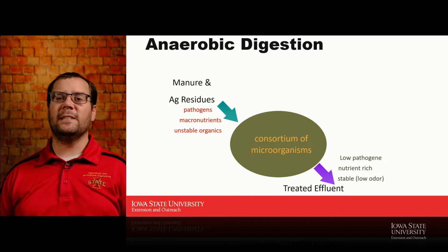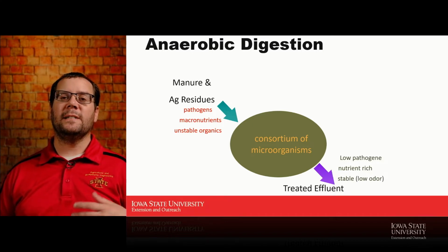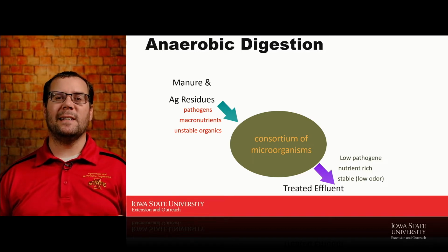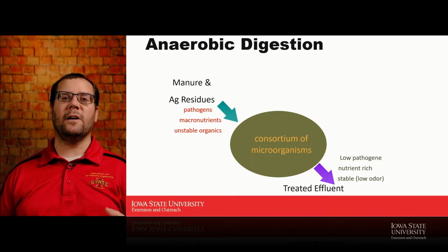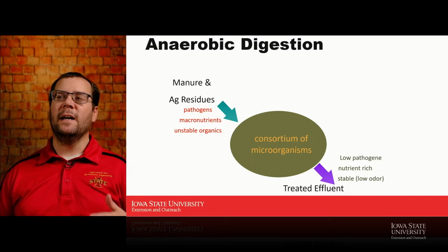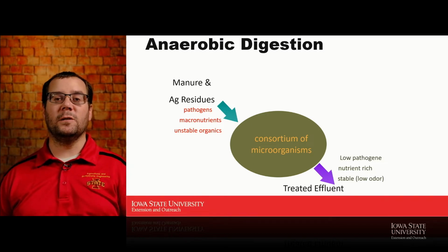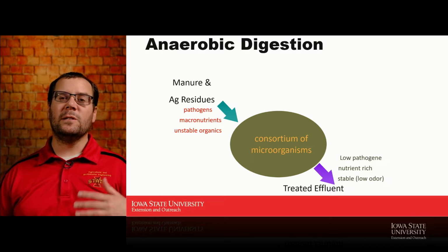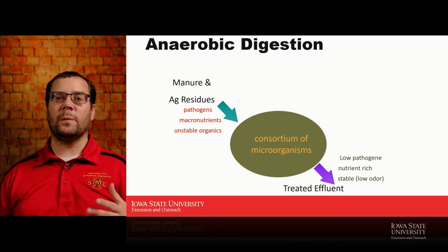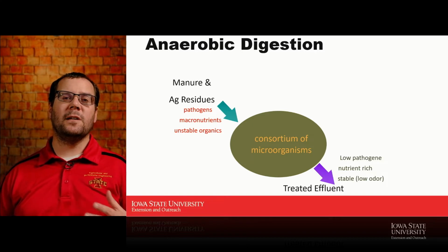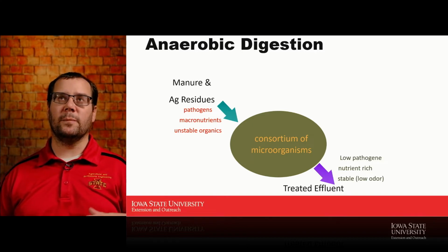And then the other big advantage is it's relatively stable. By stable, I basically mean that those things that cause odors, that decaying carbon that often leads to unpleasant smells, has been broken down and converted into CO2 and methane, both of which are odorless, resulting in a relatively low odor product. Now, it's not odorless because there are compounds in it like hydrogen sulfide and ammonia that will present some odors, and in certain situations we might want to do something with that, but it generally is much less odorous than when we started, or at least than the potential it would have to cause odors while it was stored.